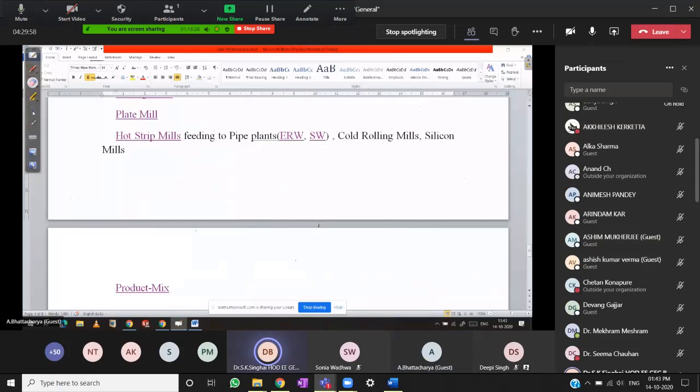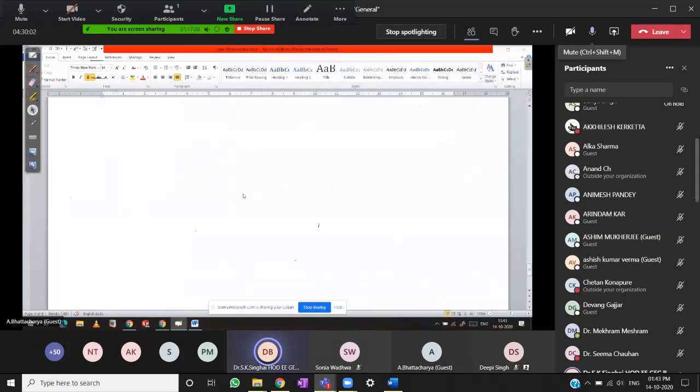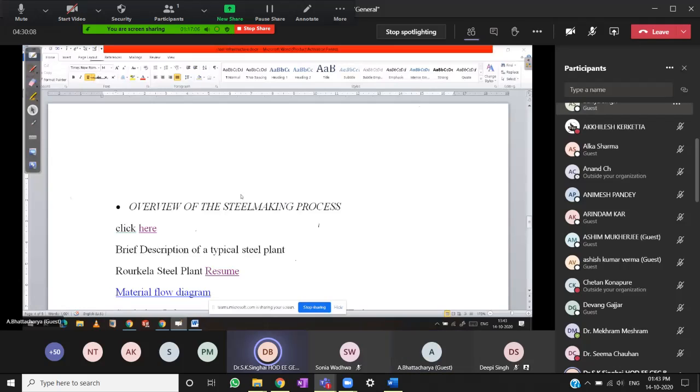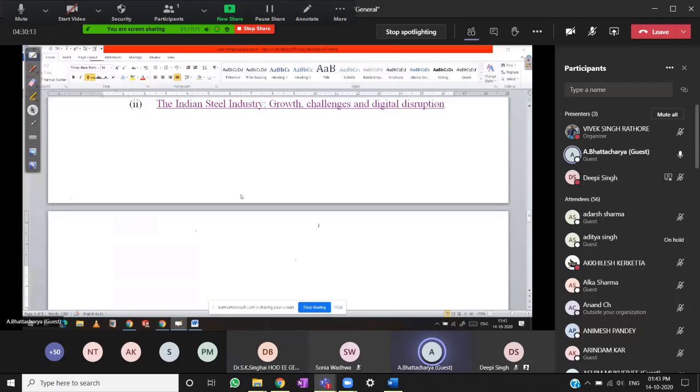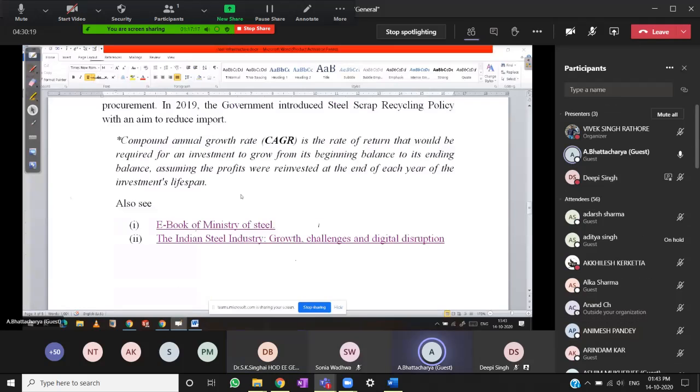Yes, sir. What is the relative disadvantage of hot and cold rolling, sir? Because what I feel, the cold rolling will take a lot of power. Yes, it will take a lot of power. You are right, but then the qualities are much superior compared to hot, and you can get thinner gauges.